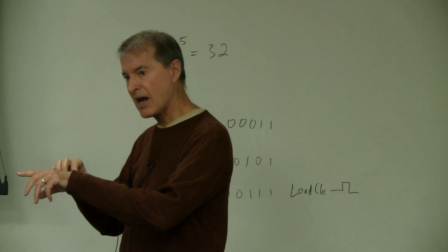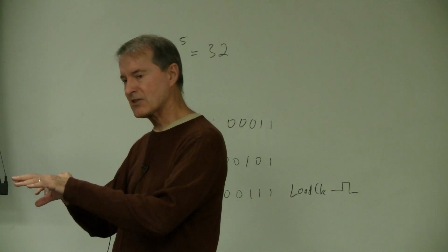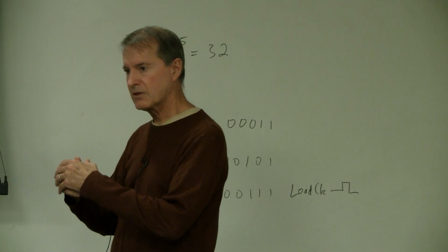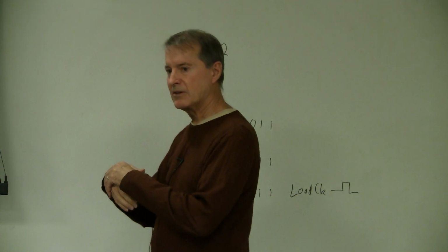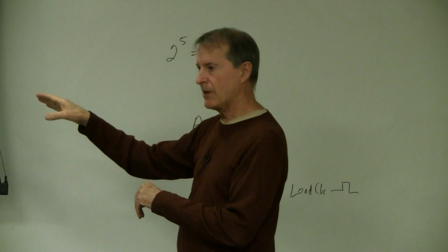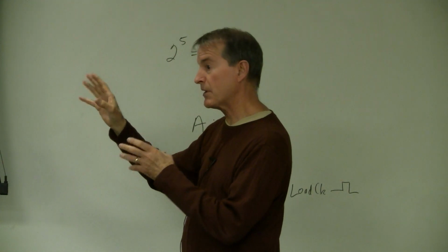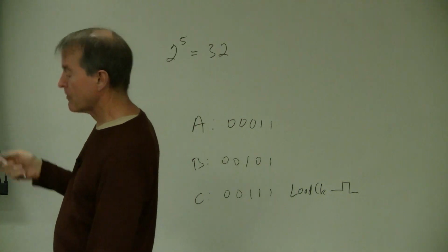But it takes time to set up the tri-state devices, to synchronize all those tri-state devices to be set up correctly so that there will be no conflicts. Do you remember? Good, that was good. Is everybody with me on this? But inside the CPU, everything's unidirectional for speed. Okay, so that's figure 11.51.